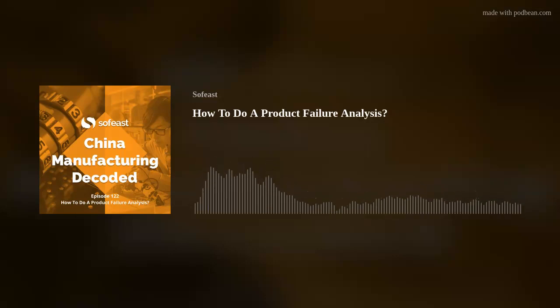And you really want to get to the point where you can describe what they call the physics of failure. This happened because of this, sort of in a chain, right? So if it's just a product that doesn't work, like, for example, tablets that are shipped out and then maybe 10% of the users say that the battery is at 0 and they cannot even charge it. Okay, so what happened here? The BMS, the battery management system, did not automatically turn it off completely when it got down to 3%.